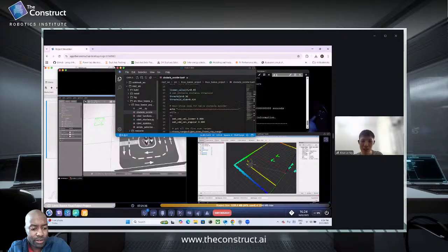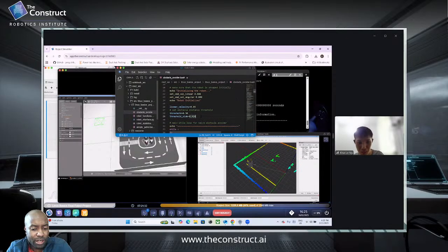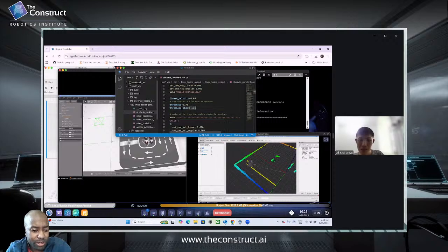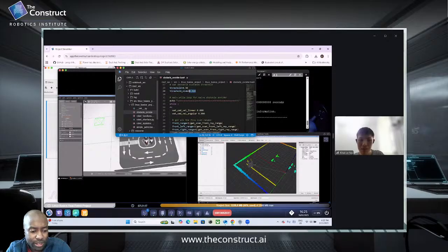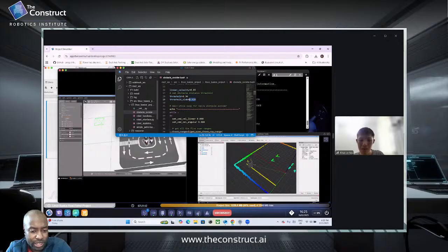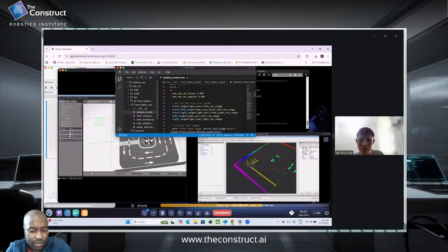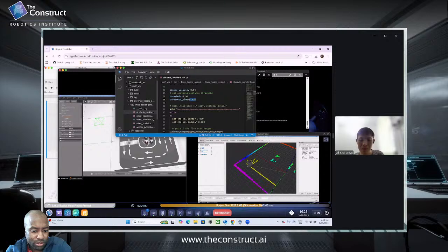Yeah. So that's why I'm asking, why did you have to pick that distance as the one that you set to be your threshold? Because it's not the index that is indicative of the obstacle that is directly in front of the robot. That is slightly to the side, right? It doesn't matter if you go to the left or to the right, but that distance is not indicative of the things that are right in front of the robot. That is the zeroth index, if you say. So to me, I think that would just make your robot slightly less predictable. It might work, but I'm trying to understand, why did you have to do that?